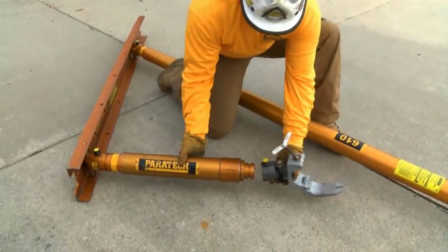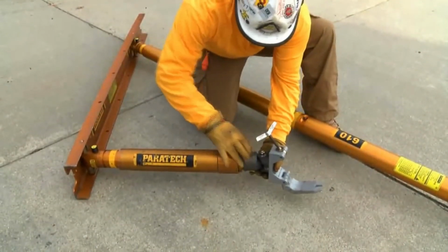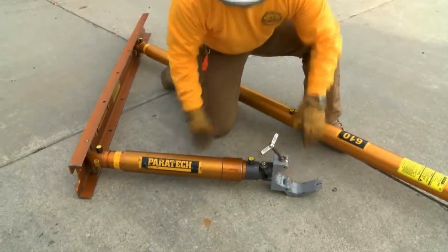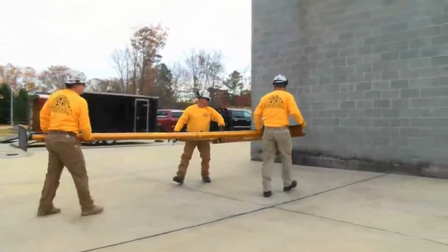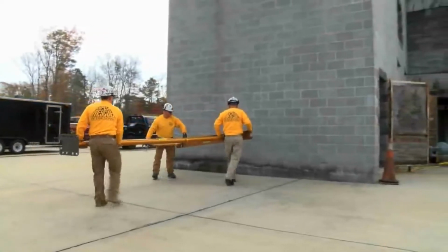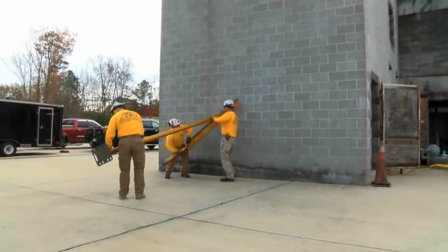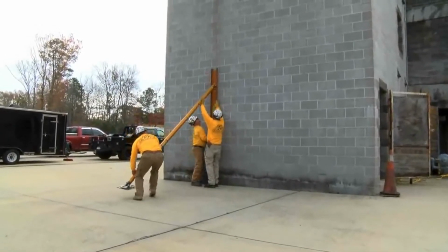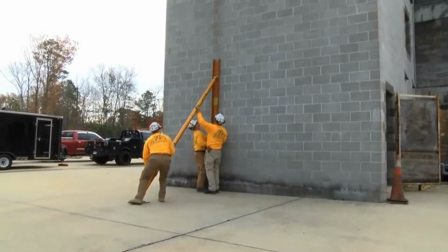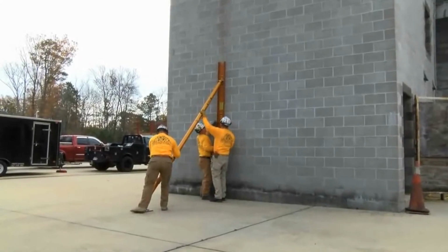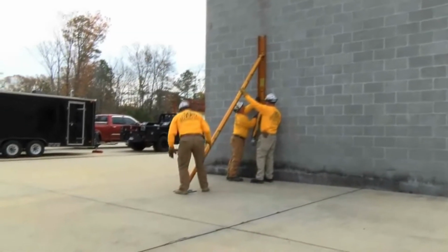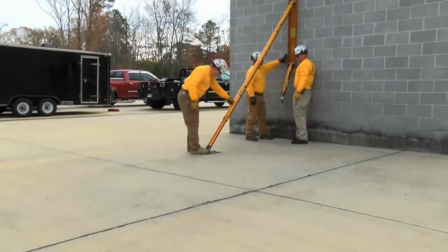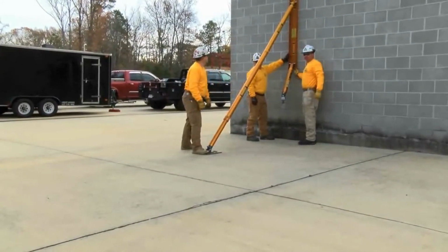Attach the clamp and clevis to the movable end of the B23 brace. Let this hang unattached to the raker strut. Move the assembly, with the brace not attached, over to the wall. Slide the top end up the wall until you reach the 10-foot insertion point. At the 10-foot insertion point, the man at the bottom will adjust the lock nut on the strut standing on the ground pad, footing it. Footing it will hold the raker in place while the brace is adjusted and attached to the raker strut.